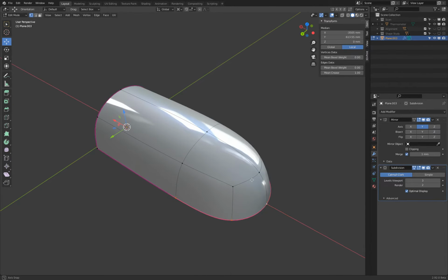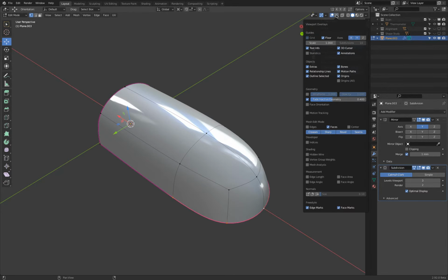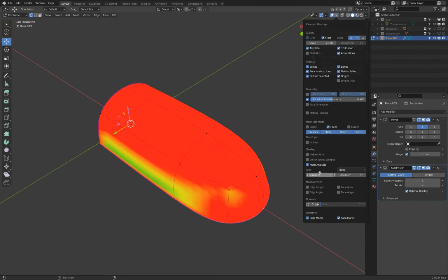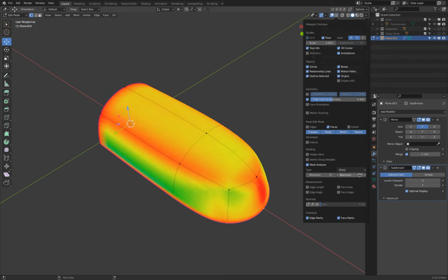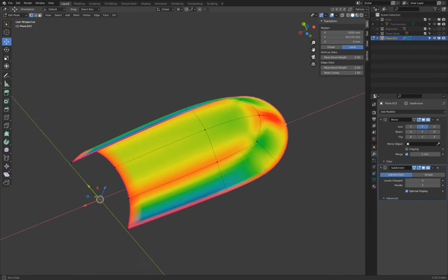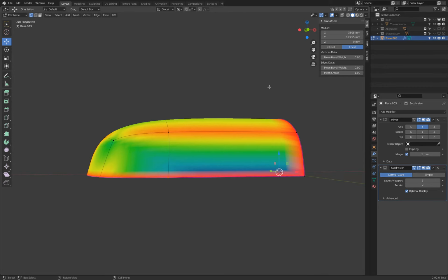And to do this technically really well in programs like Alias, this is one of the hardest shapes really to do. Possible, but very labor intensive. So let's turn on our mesh analysis tool. We go to sharp, -5 and 5. And let's slide and see, maybe 8. Yeah, okay, so these values are good. Then we can see a little bit what is going on in terms of the deformations.